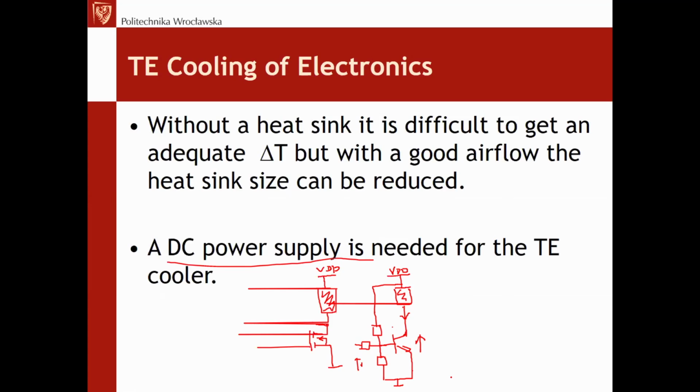So that's the disadvantage. In the case of Peltier control, you have a choice: either you drive it in on-off mode, or you have to prepare a good transistor for power dissipation, because a lot of power will be dissipated in the transistor in this configuration. Here, in this configuration with a good MOSFET transistor, the transistor will be much cooler. So the overall efficiency of this circuit is, of course, much better than here.